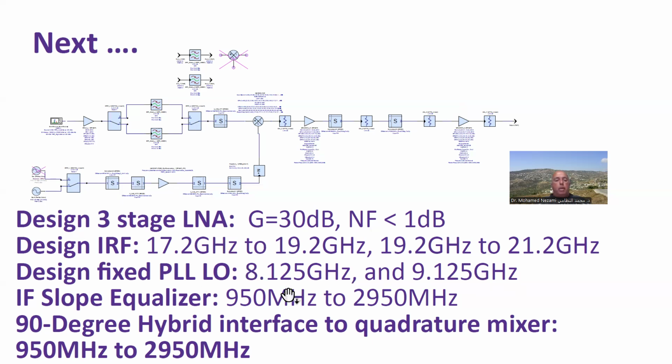So in the design, the slope on the IF, I really cannot do anything about, because this device in here is mainly what's causing that slope. And that slope is going to get exaggerated by the slope from these filters as well, because these tend to have a downward slope, and even the LNA itself.